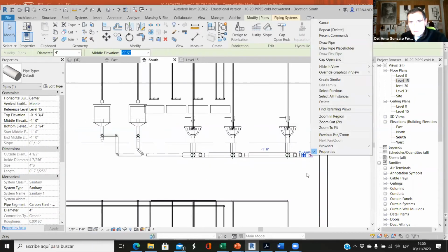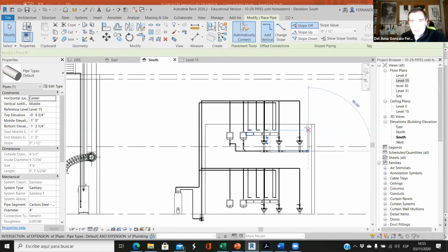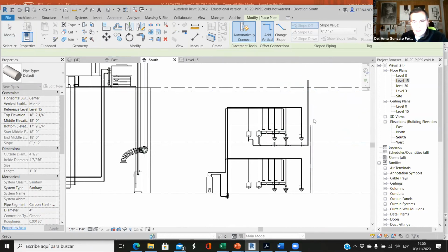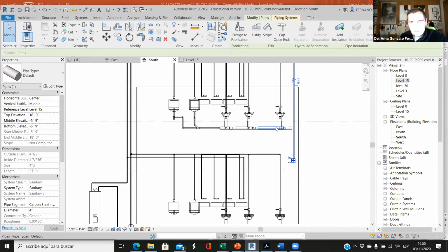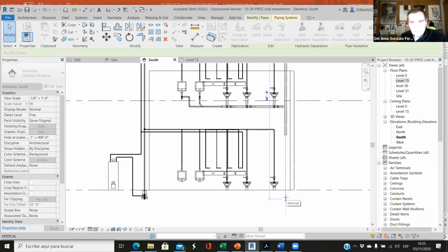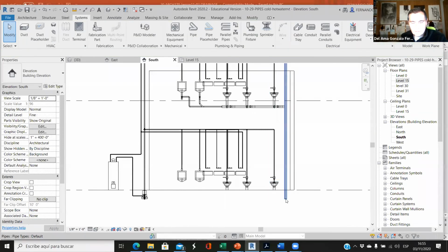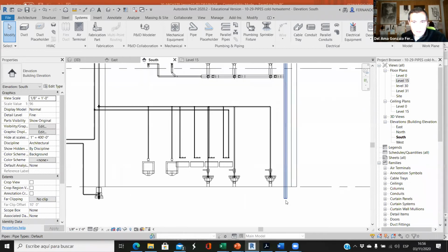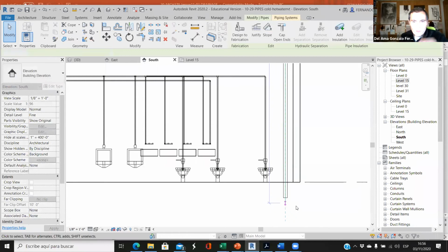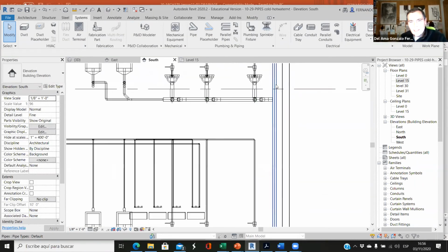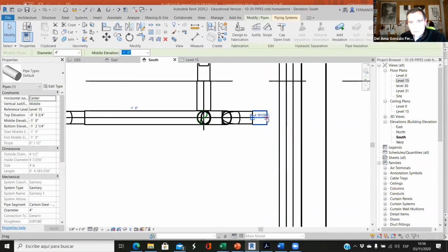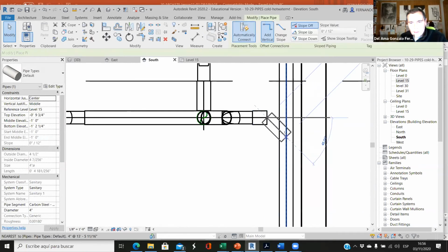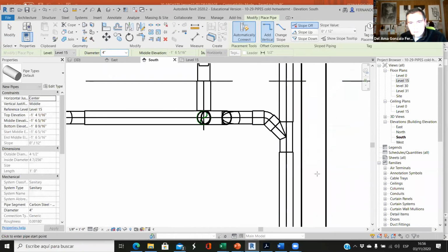Now at some point we need a vertical pipe, so we can draw something vertical. Remember that for the vent stack we need to go beyond the roof level, and here we don't need an elbow. I have to delete this, and I have to go down, all the way down, underneath the floor level, because there will be horizontal pipes, and they will be buried. And I told you that the gray water should be above this level, so I'm going to make it a little deeper. And now this, I don't like it because I think it's too close. So from this point, I want to draw a pipe with this 45 angle. There you go.